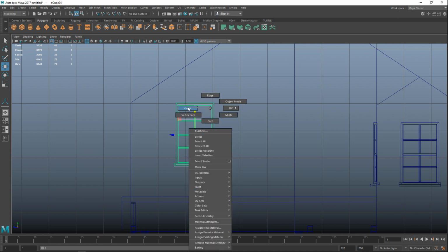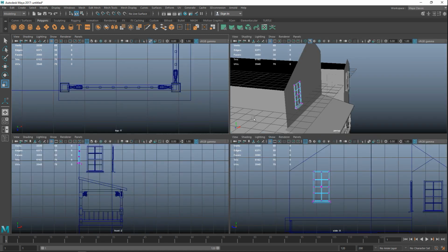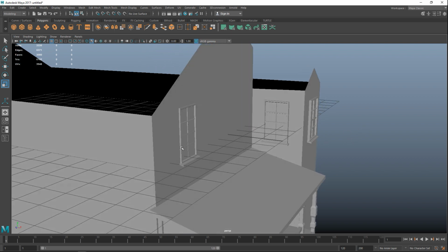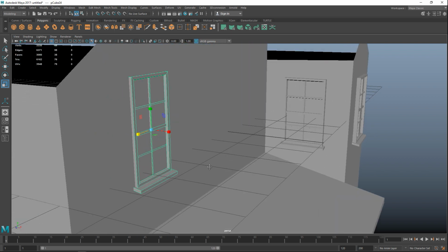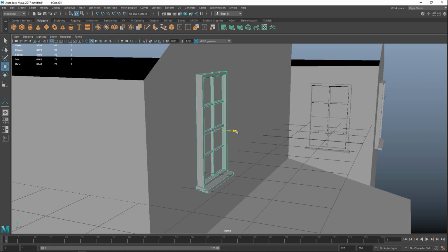So what I need to do is right click vertex, drag select these and these, and then take the scale tool and bring it in so it won't be warped, and just bring it in slightly. I just want to have a kind of a visual difference, that it's not identical to the other ones. Okay, we're going to hit W to bring that out a bit, like so.